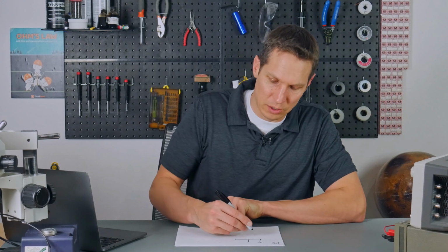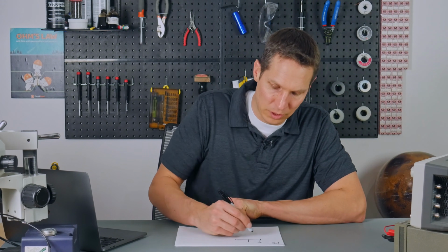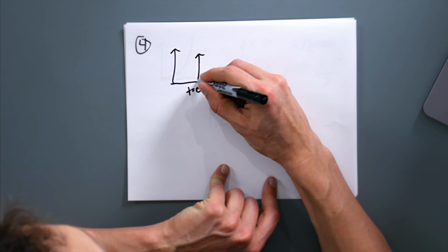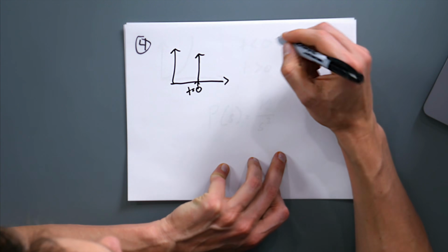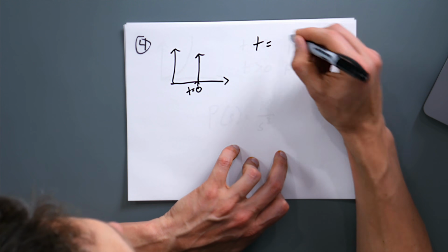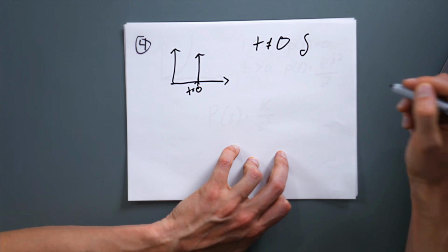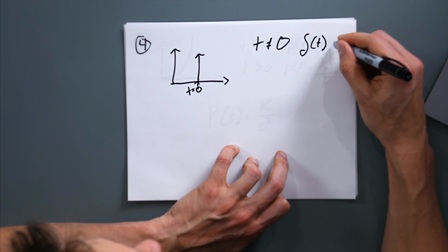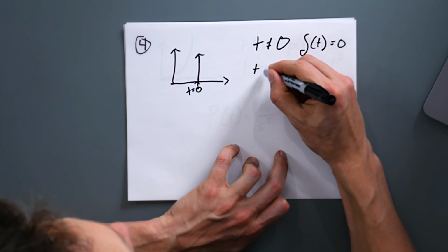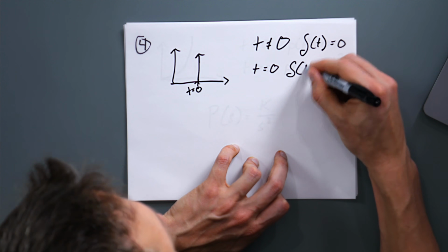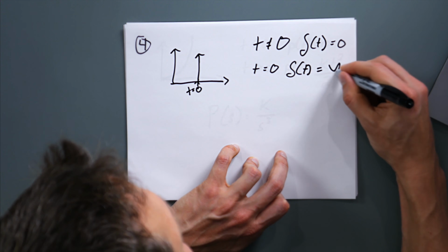So this one's a little bit harder to say what's going on in the time domain, and also I wrote that in a bad spot. Let's just call this time equals 0 right here. Here, if time does not equal 0, then the lowercase delta of t equals 0, but at time equals 0, delta of t basically equals infinity, which seems kind of unrealistic because infinity doesn't really happen in anything we do. But this is the best way to model a really sharp change.